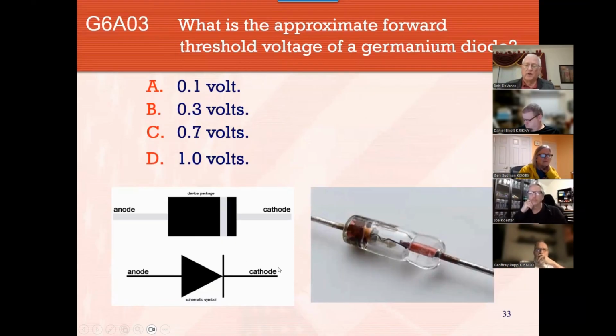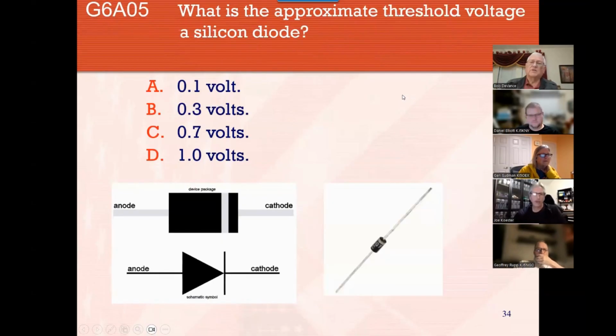Current flows through from the cathode to the anode here, and as I'm looking at this, from the right to the left. So when we're playing with our crystal radio, there's enough signal hitting in there to exceed 0.3 of a volt so that the crystal diode can work or detect the signal that's coming in. That's a whole other discussion we won't go into right now. That's the germanium diode. Conversely, the silicon diode looks generally like that.